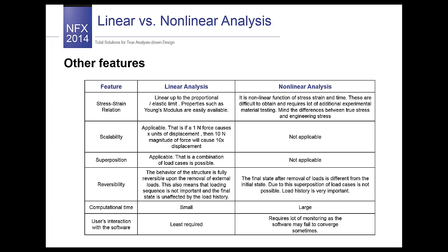Superposition, as I said, is applicable, so we can linearly combine several load cases, so we can create a lot of combinations for your loads. Reversibility is explicitly allowed, and this means that the loading sequence is not important, and the final state is unaffected by the load history.